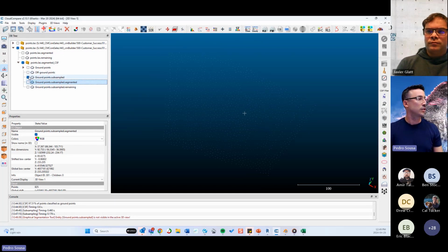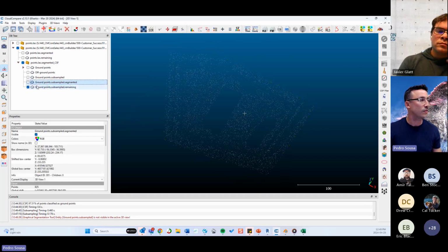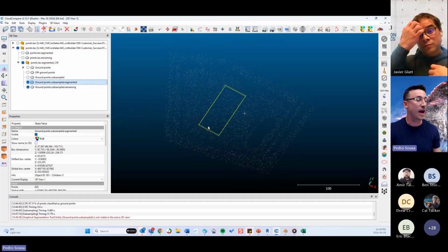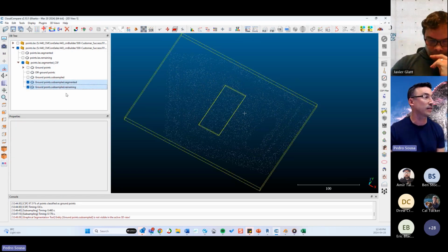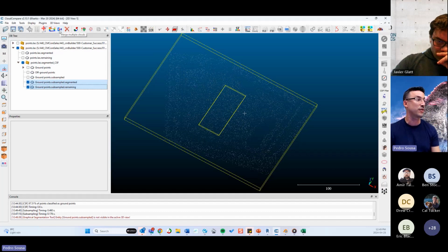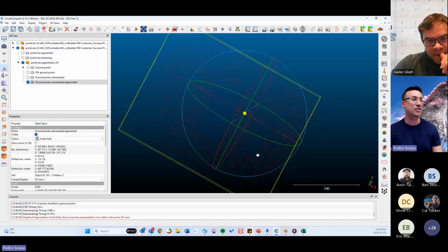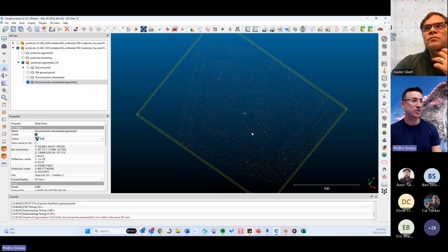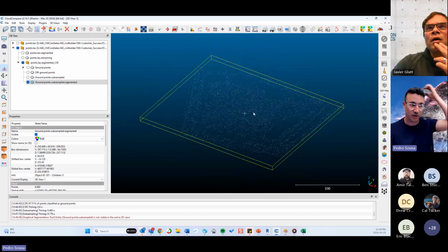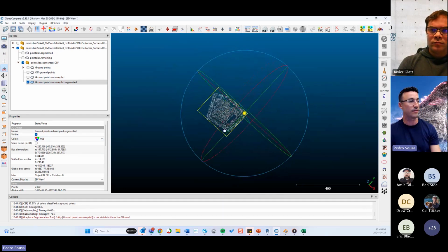Okay, so let's go back to what it was before. After you do that, if you have 2 point clouds that have different resolutions, you can select those 2 point clouds and click on this button over here, and you're going to merge that point cloud. It will give you this change of color that's called scalar field, but you can go over here in colors and change to RGB. So it will show you the original colors of those points. If you zoom out, you're going to see something a little bit closer to what you had before.